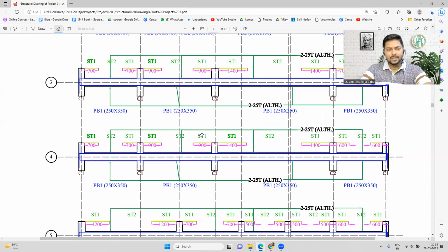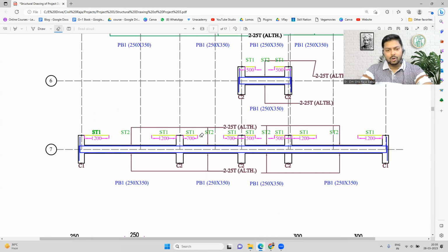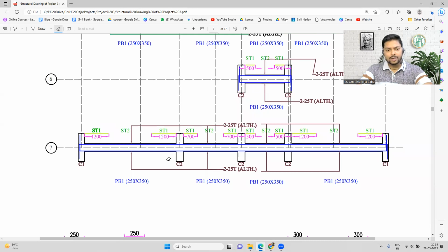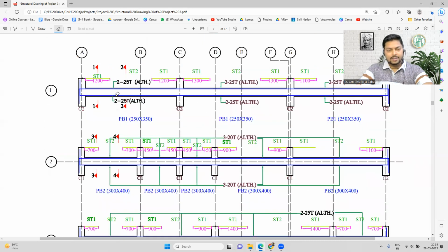Now let's see if you have any other condition. So all the conditions are being supported. One more thing: suppose this beam has to continue like this. Over here in this support, we will not provide any development length like we have provided in axis 1A. This bar will continue, and if this bar ends because of any reason, then we can go for the lap.